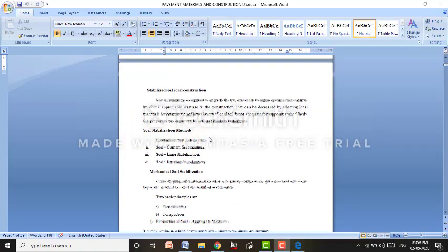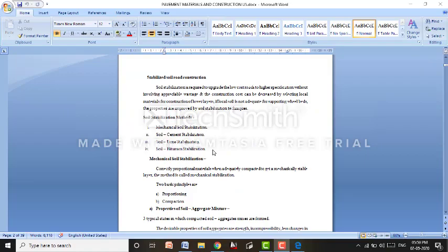Now before we start with the preparation of soil and why we need to go for soil stabilization, first we need to understand why we need to do the earthwork. After completion of profile leveling, maybe by any of the means, maybe by totalization or manual means, while analyzing, we will be comparing the centerline elevation. Once you fix the centerline, you will be knowing the centerline levels, and based on the requirement of the project and based on the design needs, we will fix the formation level.